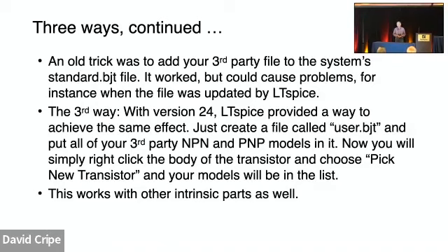Well, the latest version of LTspice, they've thought of users, and they created files called user. They have their file, I forget what the base name is, but it's .bjt, but you can create one of your own called user bjt. It will look for that. It will treat the transistors that are in there the same as the transistors that were in that database. So when you click on transistor, you'll find it in there. And it's not just transistors, all those fundamental intrinsic type ones, you can create databases for those.